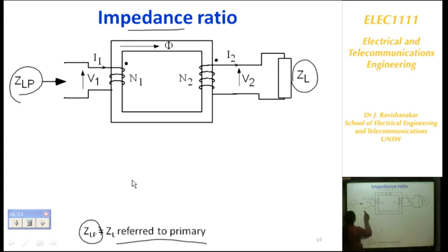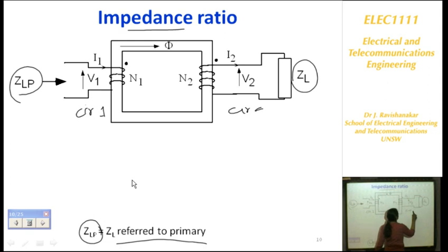Because we have one circuit here, circuit 1, and another circuit for the secondary, circuit 2. When you are doing the electrical analysis for transformer circuits, you need to solve two different circuits. Moreover, we also need to find the coupling effect in between. We need a connecting equation between the first circuit and the second circuit, and this is going to be really complex. To prevent this, we can draw an equivalent circuit of the transformer by transforming all the parameters of one side into the other side.